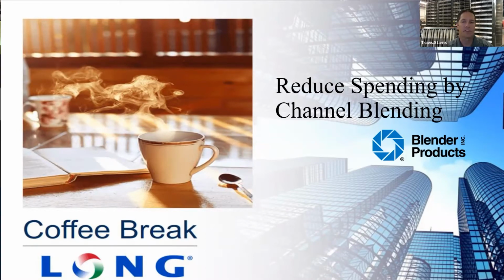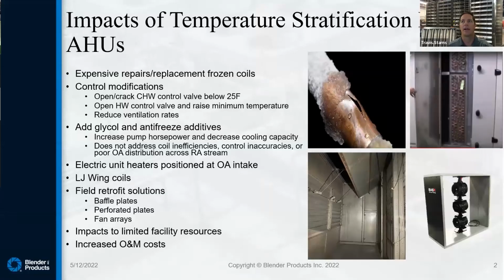And so for a little over 60 years, we've been a small niche company that solved a niche problem within the HVAC space, and that's around stratification. So on this slide here are a few bullets around temperature stratification. There could be velocity distribution inside the plenum, with uneven loading to the coil that could impact the performance of the coil when trying to remove water in the airstream, i.e. dehumidification, or uneven loading to the filter section. All those types of things we get involved with.